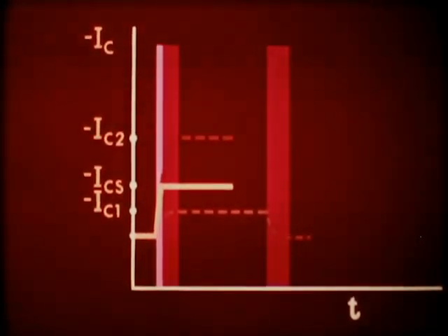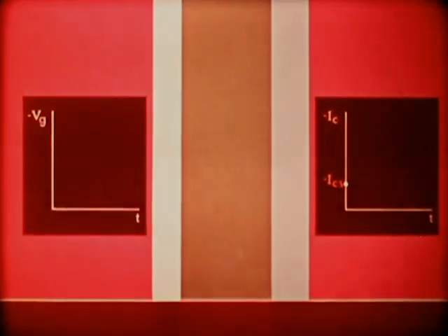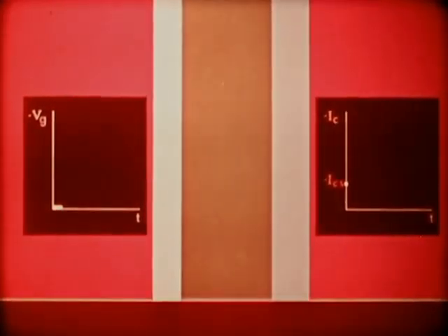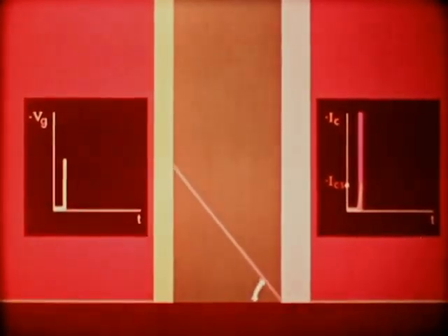This effect can also be explained from the concentration curves. Consider first that the transistor is working in the normal state. As soon as this stepped voltage pulse is applied, the transistor will continue to operate in the normal state, and the collector current will increase as a function of the angle formed by the whole concentration curve.